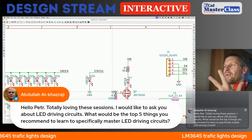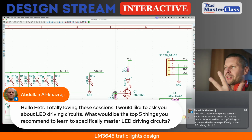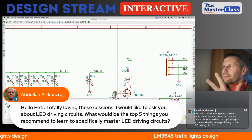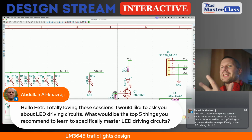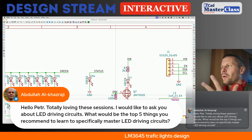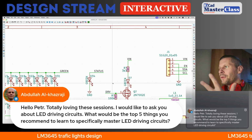Why is that? When your MCU or logic device port is floating, this resistor sets the gate-source voltage drop to literally 0. So, simply said, it keeps the LED driver off in the off state when there is no driving signal of a high level.